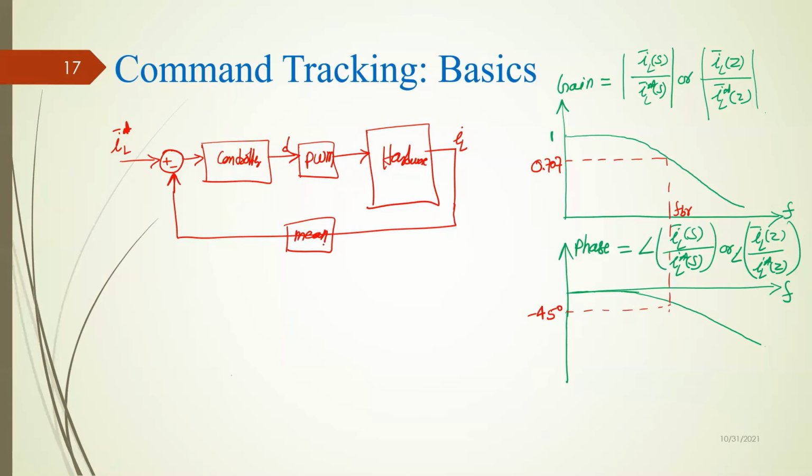Okay, so this is how it looks. Now, if you want to get the Bode plot where the x-axis is frequency, you need to add harmonics into this reference value. So what we will do is realize the reference average inductor current as DC plus AC. Here I have chosen DC as 70 ampere, and AC has a magnitude of 10 ampere.